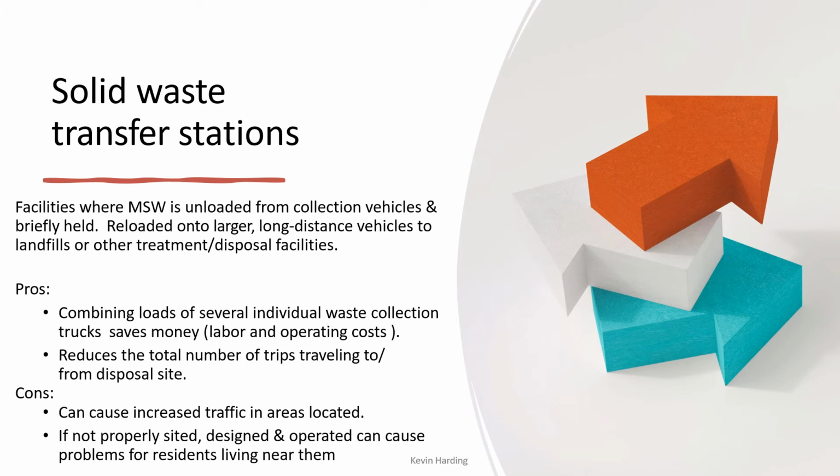So this is now a new line of thinking, a new topic. One of the ideas with solid waste management, to try and manage the amount or the processing of solid waste, is to have something called a solid waste transfer station. This is a facility where the municipal solid waste is unloaded from smaller collection vehicles. It's often held there for a short while of time. It can have separation at these sorts of areas. It can have not necessarily recycling, I don't think, but it has various intermediate roles before it gets put onto larger long-distance vehicles to take to landfill or other treatment and disposal facilities that are further away.